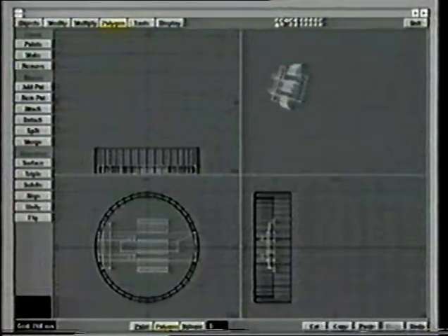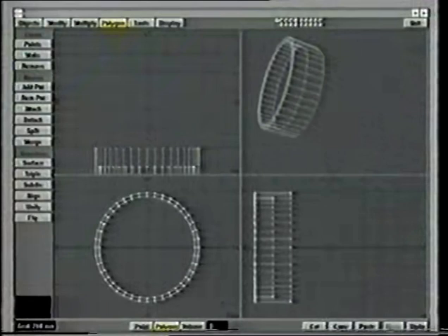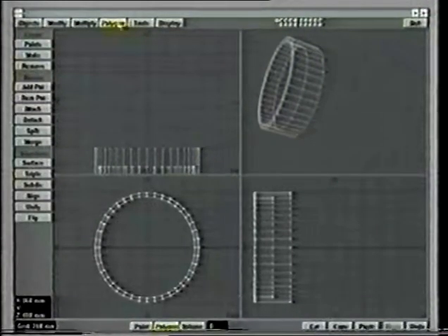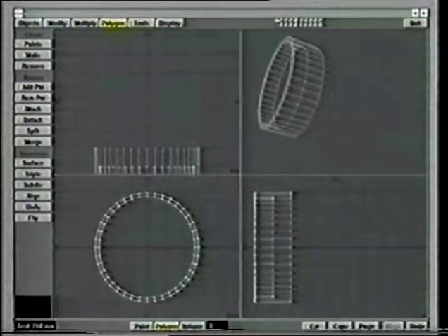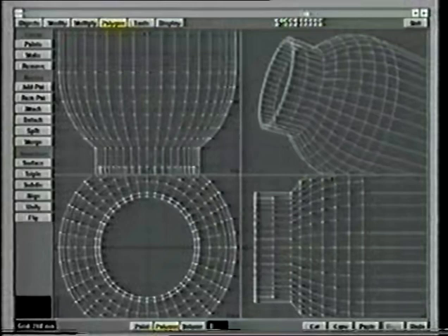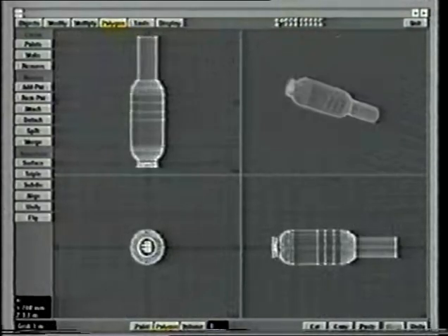So one thing that I haven't done is I haven't named any of the surfaces on the front here. So let's polygon surface, we'll call this dock ring. Okay. And I'm going to paste this onto our fuselage. We get our hinge here. Paste that also onto our fuselage. So let's have a look. What have we got? Well, we've still got basically a sausage with a rod out the end of it. So we still need to keep moving on here.